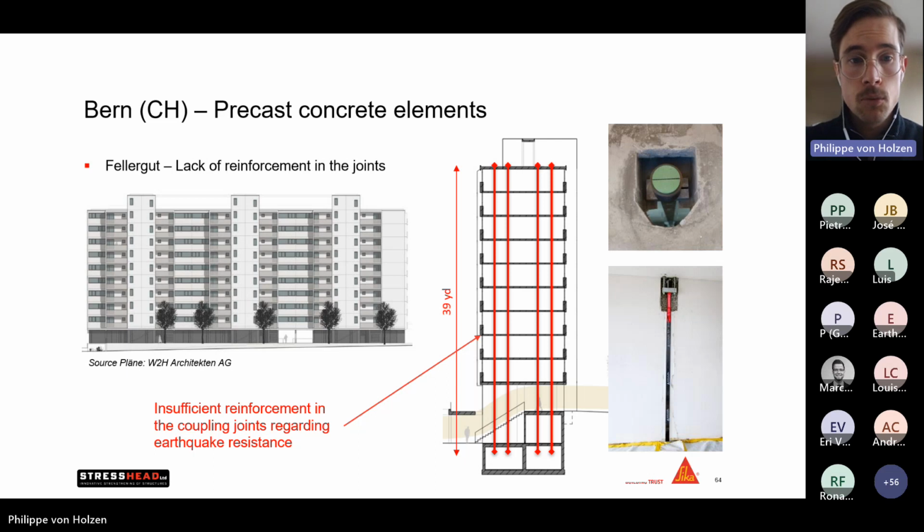Now, a very smooth solution that we were able to provide was installing here the anchorages on the rooftop and in the basement. We were able to pass the tendons and install and tension single plates over the height of the full building without interrupting the tenants living in this building itself. And we were able to reinforce this whole building in just a couple of days without any interruption.